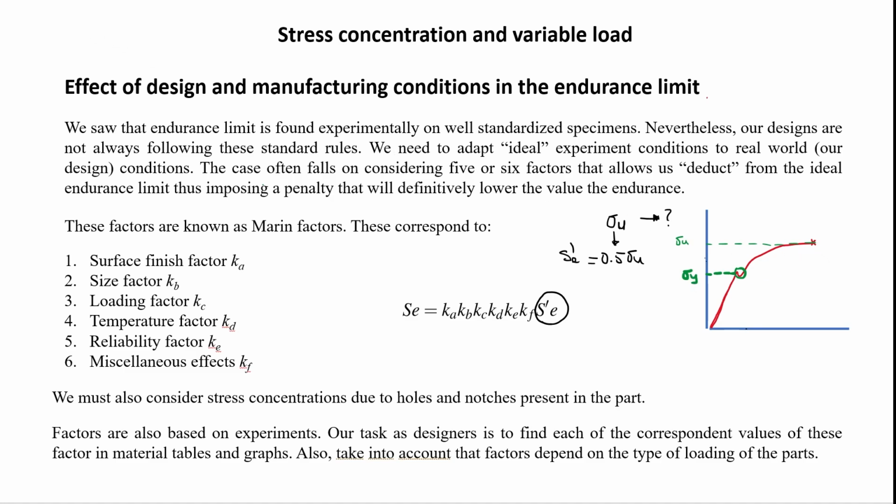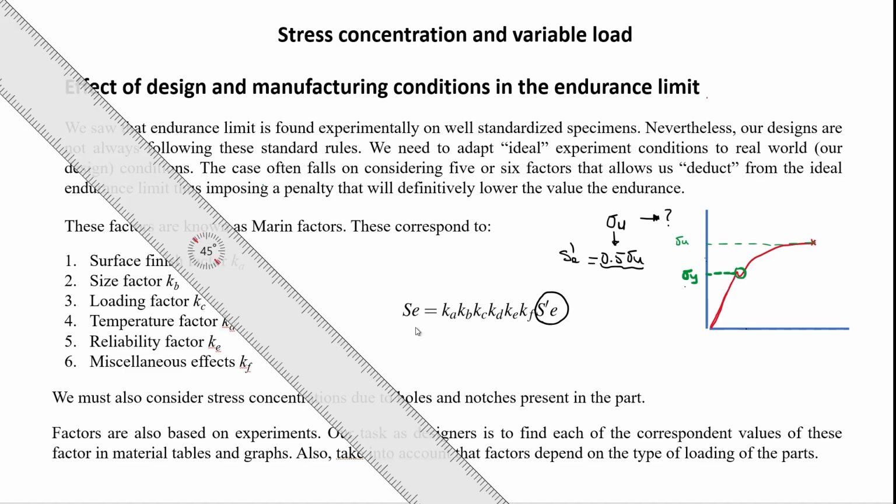Now, what are we doing? We are saying that if you want to consider fatigue, divide the ultimate strength by half. So if I try to do that proportionally in this kind of graph, it's going to be something like this. Let me put the ruler better.